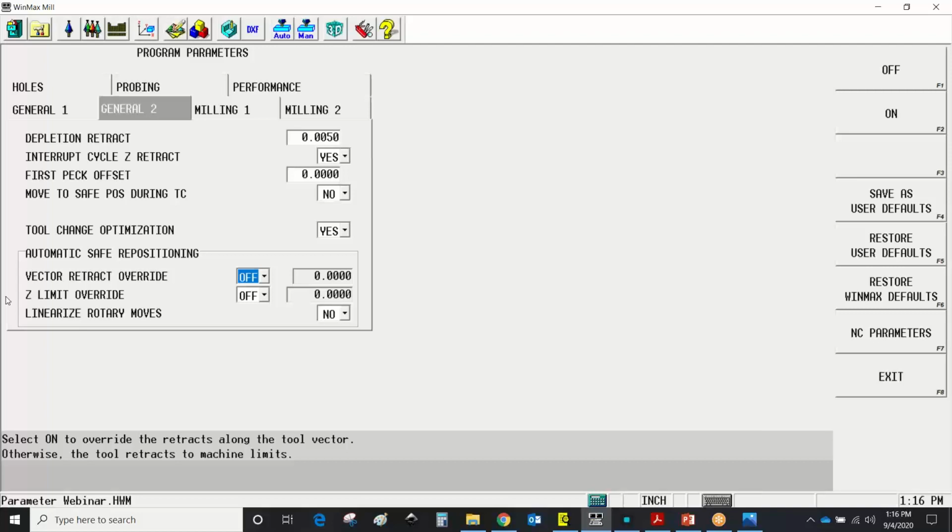We do this every time we sense a transform plane change in the program, we automatically do that. We'll retract all the way out to limit, and we go all the way home in Z. Well, sometimes people want to be able to control that and not retract as far. So you can simply turn these on, and then that gives you two fields here where you can adjust how far away that retracts before the Z moves and whether the Z goes all the way home or not.